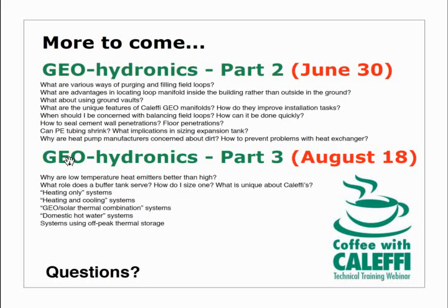Yeah. And Hydronics 9 goes through the whole procedure of how to set up a purge pump and set up hoses to essentially flush the air out and get the fluid in. Most of that plastic will probably come out at that point, too. Yeah, that's a good point. I mean, that's the same with the hydronic system or snowmelt or anything. You want to do most of the big heavy lifting on the dirt removal with your initial purge, but certainly anything that's left in there, you want your separator to be able to handle properly.